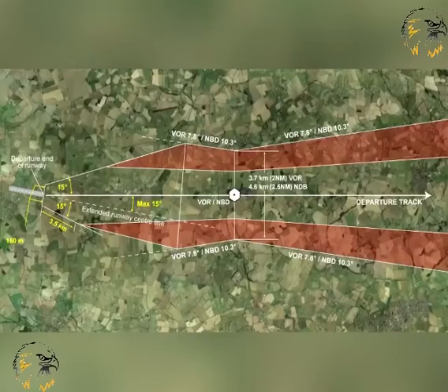A straight departure is one in which the initial departure track is within 15 degrees of the alignment of the runway. Track guidance may be provided by VOR, NDB or RNAV. At this point, we can usefully mention colour coding. The shaded areas are considered secondary for minimum obstruction clearance, whereas the clear areas along the departure track are considered primary. We will look at this in more depth later.